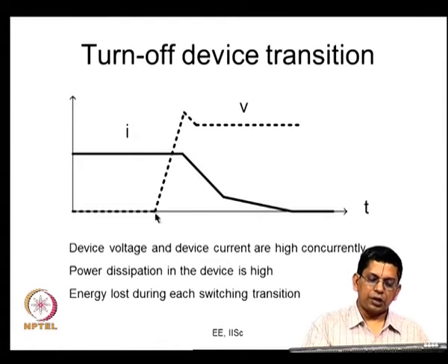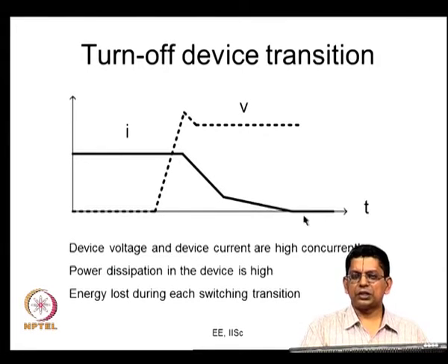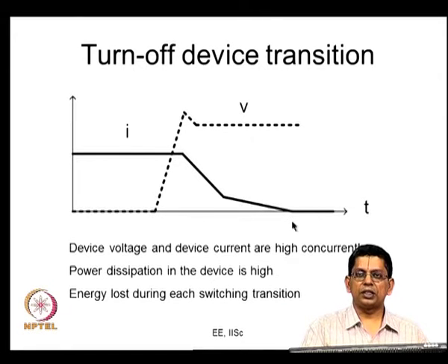That is, this is before the turn on. So during this time it would have been conduction loss. This drop would have been the forward drop, which is actually very small. Again here the conduction is 0. So this is the off state, there is no loss now. But over this interval from here to here, you find that there is a good amount of power dissipation.